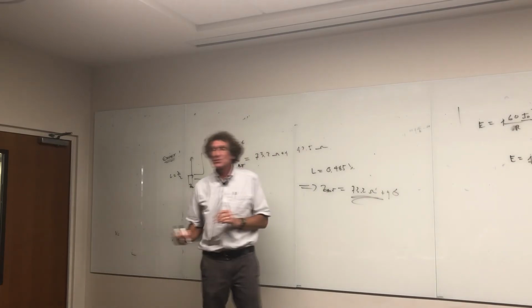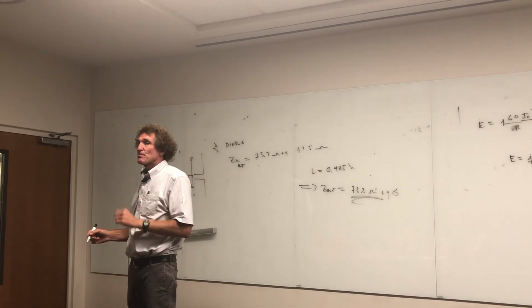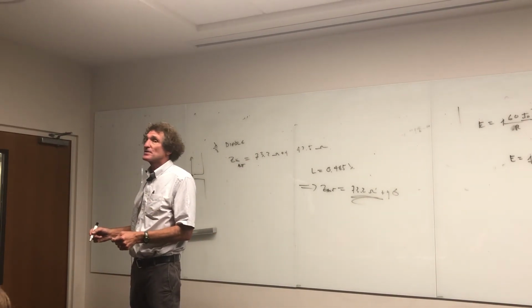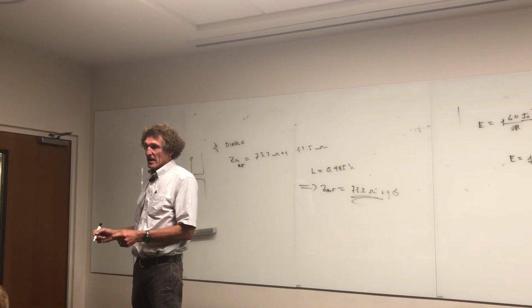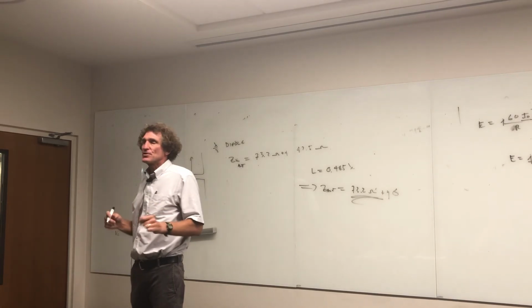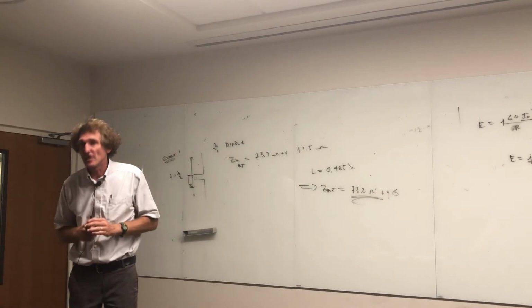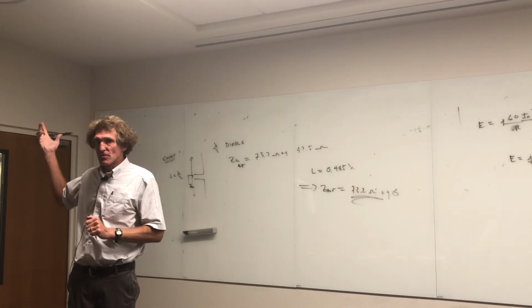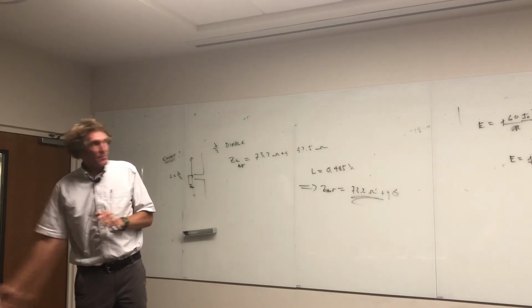In other words, there's no reactance. That's preferred because reactance doesn't do anything to help us radiate. It's just more AC resistance to push against to get current into that thing, so we need a larger voltage. Got me, guys? This is real important.